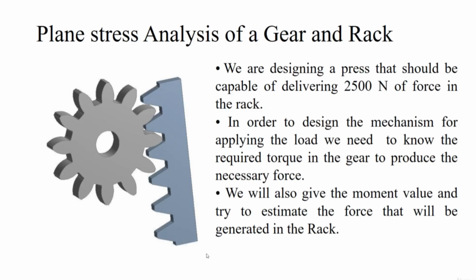In order to design this mechanism, we are going to apply the load here and fix this particular gear, and we are going to find out how much moment is required to be applied here so that the force at this particular point of the rack will be around 2500 newtons. That is the first case.